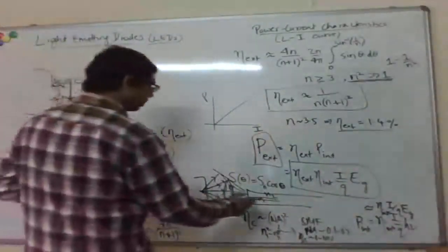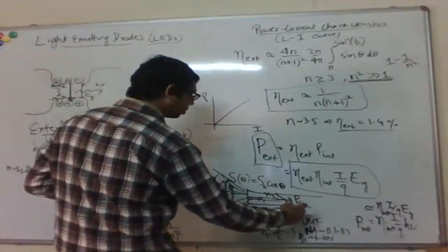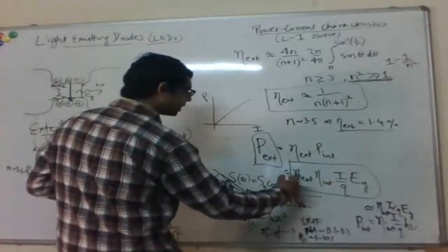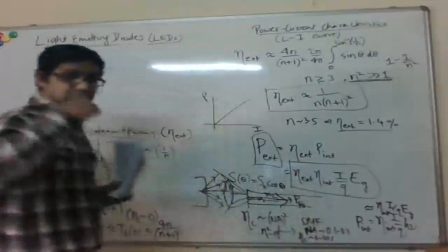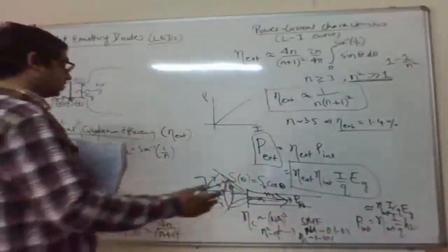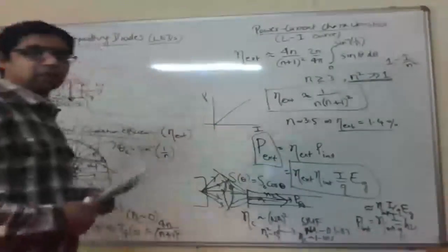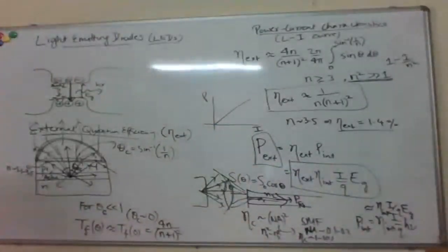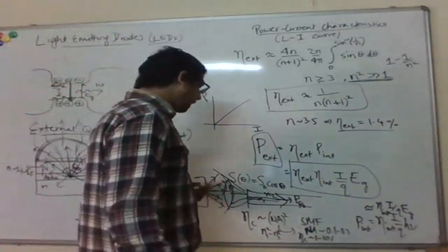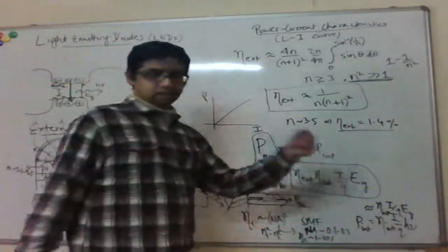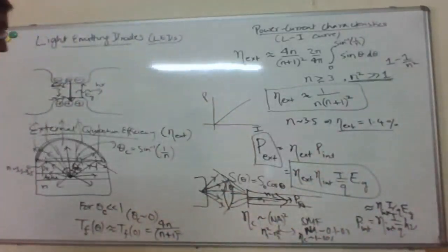Right? So if you're interested in how much power is coupled into the fiber, that's an additional coupling coefficient here, which is again like 1 to 2%. Okay, so that again decreases the power by more than an order of magnitude. So for these reasons, basically, with LEDs, you're not getting much power into the fiber for communications.